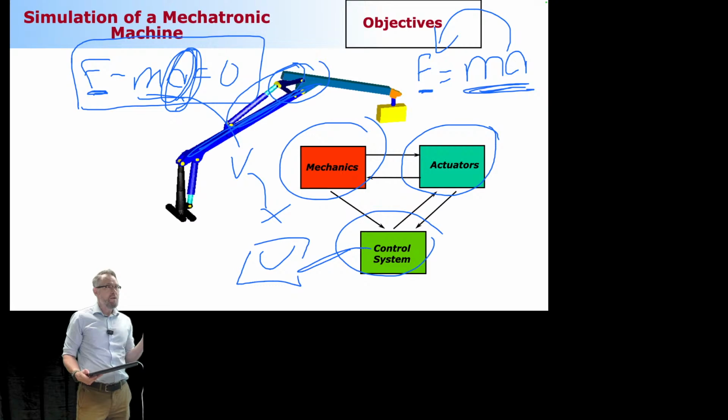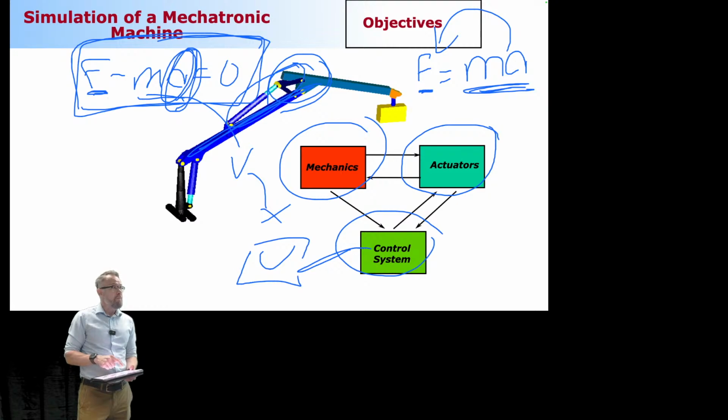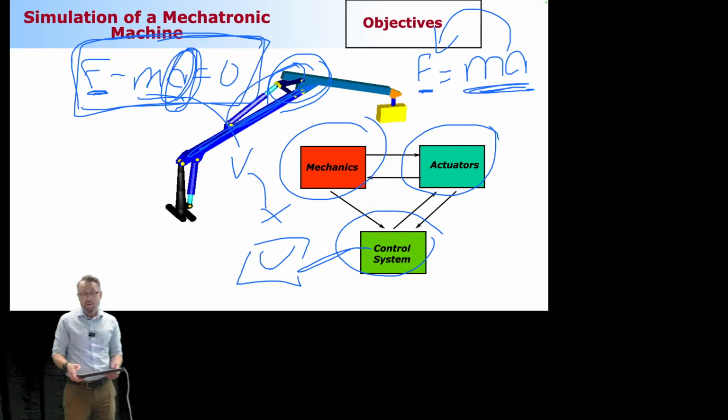There's one missing component called constraints. Because in this equation of motion, a body can move as it wants. There is no constraint. Whereas in a 4-bar mechanism, you know that this is not the case. Each of the bodies moves with respect to the others. How to take that into account? We're going to focus on that a little later.